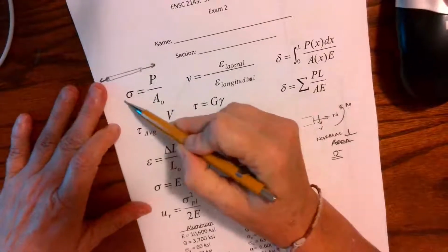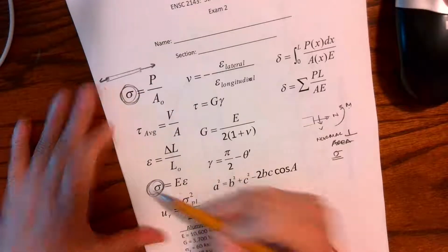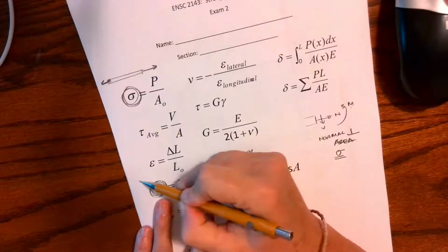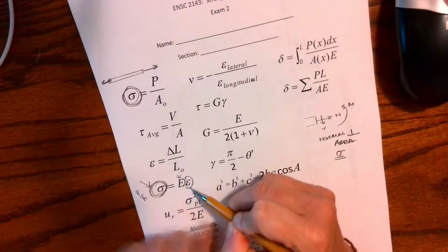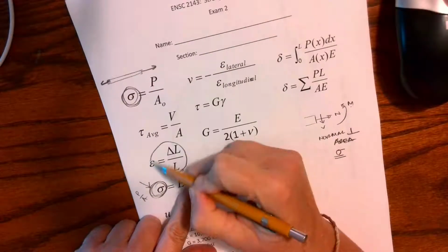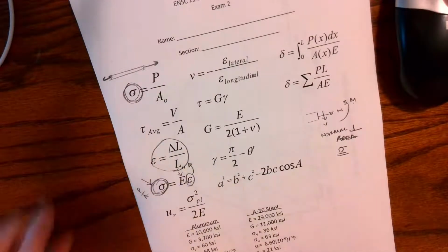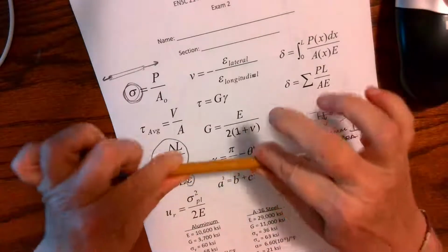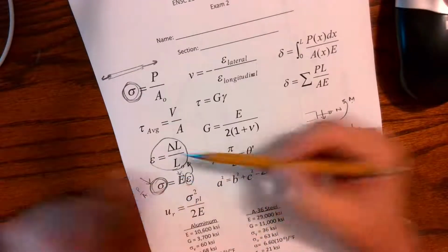I can also say, okay, what equations go with that? Because they're kind of spread out, and I can see a sigma down here. So we have P over A, and then we also have the relationship for my force in area, the material property, and strain. Okay, well, what is strain? Well, strain is change in length over length. It has to do with how much stretch we have. If I have a rubber band and I pull on a rubber band, it's going to have a lot different stretch than if I try to put the same force on this pin. So I can have the same force in area, but because my materials are different, I'll have a different strain.